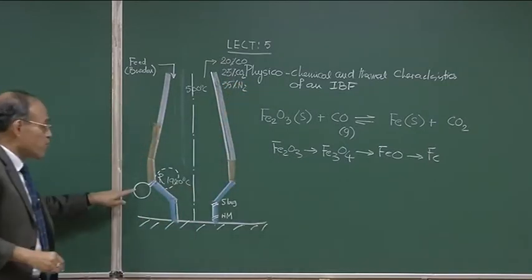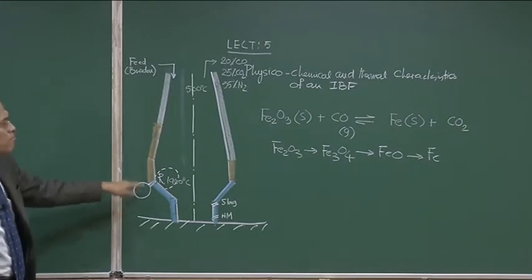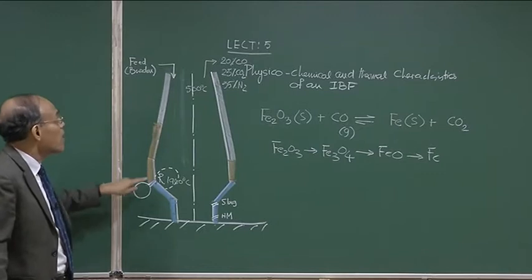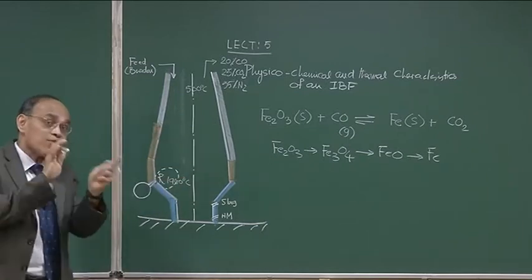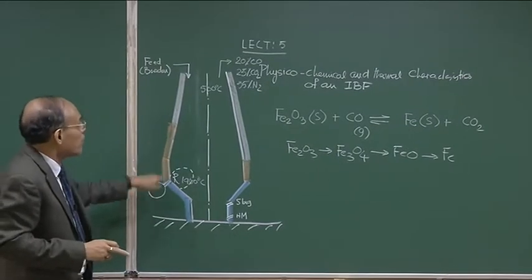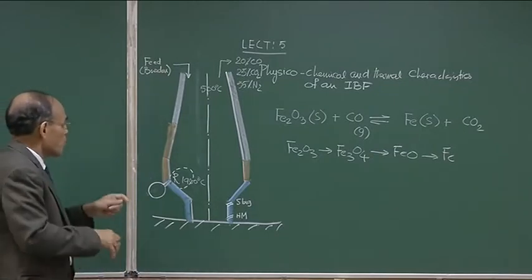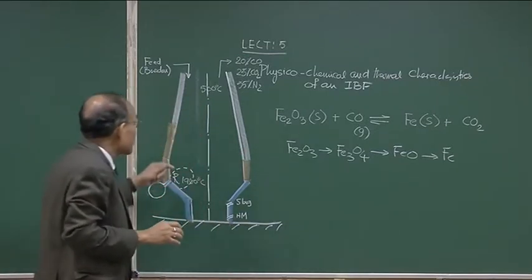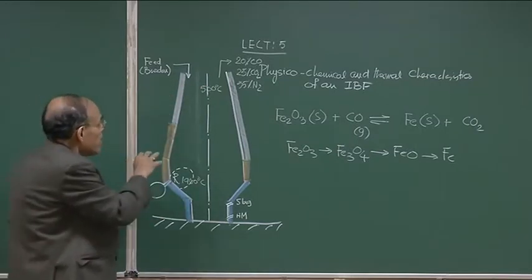We must understand that nitrogen which is injected, or which comes via the air phase, is inert; it does not change significantly. So there is only a dilution effect. Air contains 79%, but in the overall gas mixture which comes out, the relative proportion of nitrogen changes, but the nitrogen remains conserved. Whatever nitrogen you put into the furnace via the air phase is the same quantum of nitrogen which goes out, barring little changes here and there, maybe little dissolution and so on and so forth.